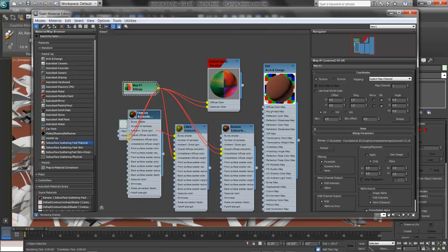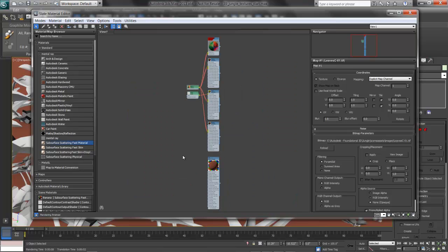If you'd like, you can arrange this or lay out the materials by pressing L. There's the layout. What we can see here is there's our 4 materials that all share that common map and my dirt down below. I'll take these materials and press H to hide their properties. This way it only shows the selected maps, and I can rearrange this graph a little bit. I'll pull the pieces together and pull the dirt up.